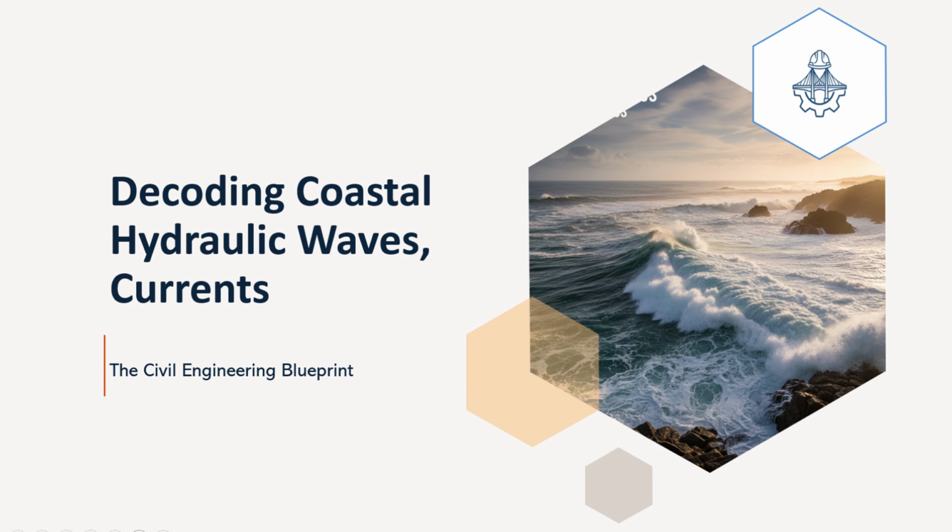Remember, a wave with period T equals 8 seconds travels from deep water to a shallow beach. Its height is 1.5 meters at 10 meters depth. What is its height at 8 meters depth? This isn't just theory, it's the kind of calculation for understanding hazards or design. Exactly. Let's apply the shoaling coefficient logic step by step.